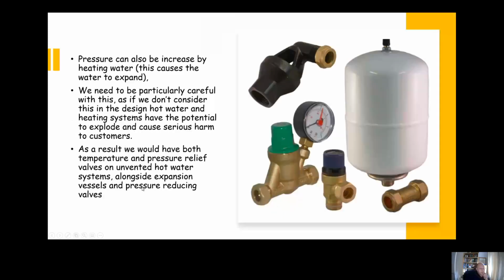And we can change the pressure actually by heating the water sometimes, because as you heat the water, it causes the water to expand, and that will increase the pressure. We need to be very, very careful with this, particularly when designing unvented systems, because if that water expands too much, it can cause pipes to rupture, can cause damage to components, and could potentially cause some serious harm to customers.